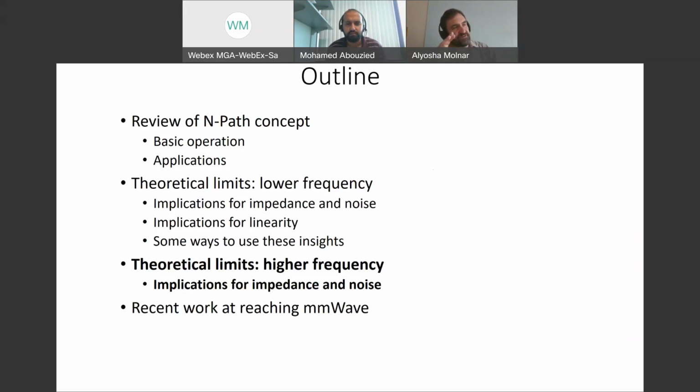When your amplifier starts to lose gain, then the input impedance stops looking like an AC ground. And then you get the worst linearity effects in the transition band, because you no longer have a good AC ground from active feedback, but you don't yet have a good AC ground from a shunt capacitor. And that's where the trouble tends to arise. So I don't have the best answer for that, but that's the simple version.